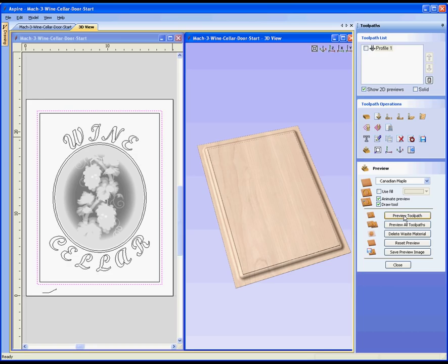So I can see that I've got the shape in there, but it's actually rounding the corners, and that's standard procedure because on most profile toolpaths you're just cutting the part out and you're not worried about what's happening as the tool rolls around the corners here because the material's been removed. So what we actually want here is for the tool to almost come past the corner before it carries on around the edge so that I get a sharp transition.